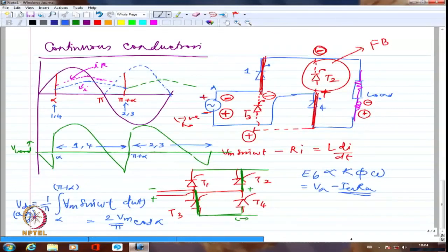And a charging station these days, at least currently, will take 6 to 8 hours to charge a battery. Right? So you can't really think of going anywhere until the battery is completely charged. So power electronics research is going towards increasing the rating of these rectifiers which charge the battery. So you want to push 300 amperes, 400 amperes of current in one go. Can we do that? Whether the battery will be able to withstand that, whether our rectifier will be able to deliver that much. So a lot of research is going on in that particular area. So this is one of the applications of the rectifier.